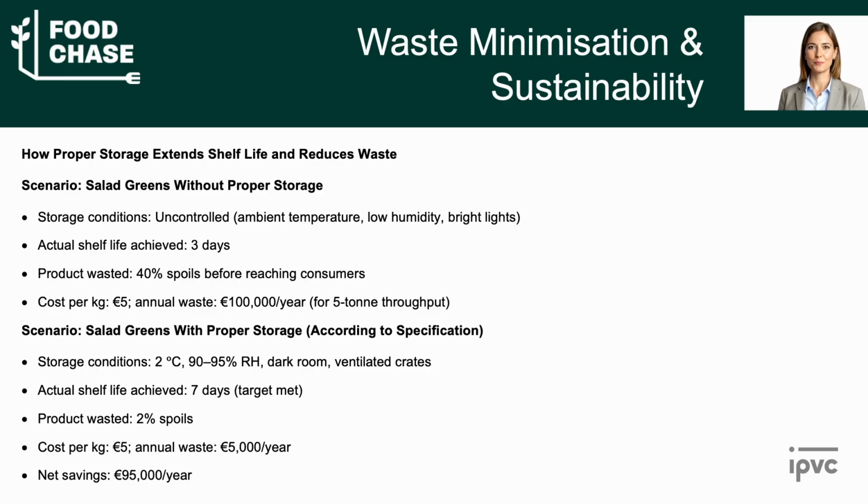Now, if you implement proper storage, a dedicated cold room at 2 degrees, high humidity, dark, good ventilation, you achieve your 7-day shelf life target. Now only 2% spoils. That's the same 5 tons a week, same price, but only 500 euros per week wasted instead of 10,000. Annual savings, 475,000 euros. That is not a small number.